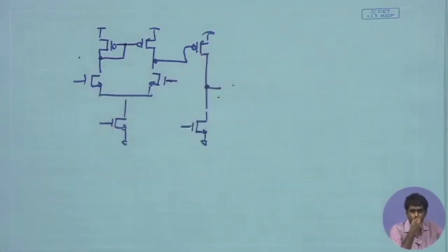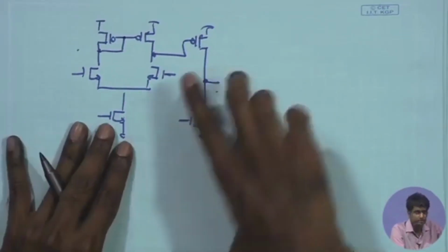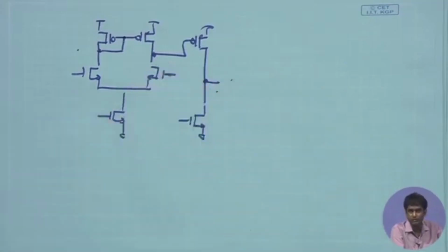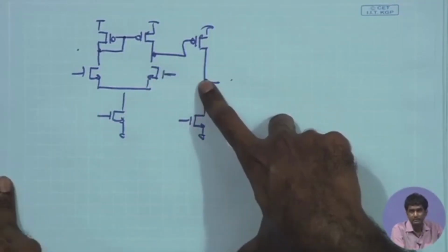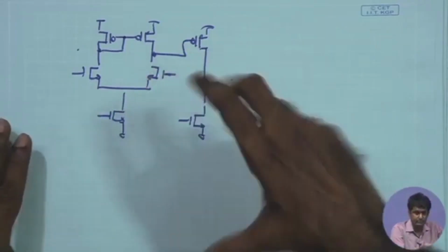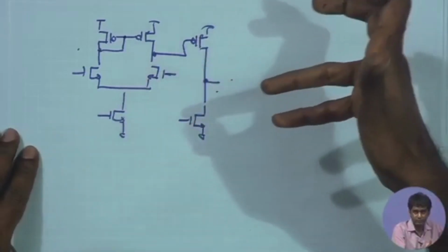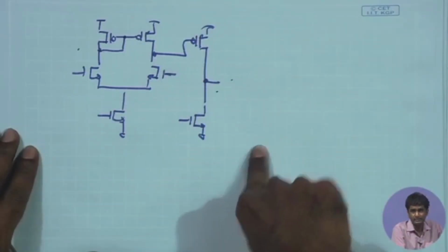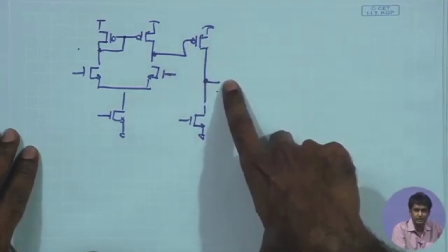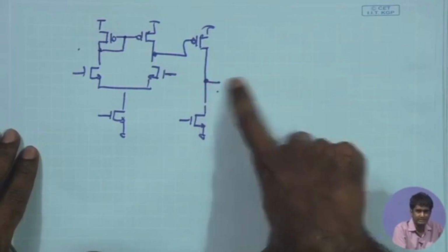For the differential amplifier or fully differential amplifier, we have taken help of the common mode feedback to set the output to that point. Here that is also not feasible because it is a single ended output and we cannot really take a common mode feedback to stabilize this. If we do take a single ended approach and try to figure out something like the single ended version of the common mode feedback circuit, it would require a very large RC time constant for providing our low pass filter and extracting only the DC component from here.